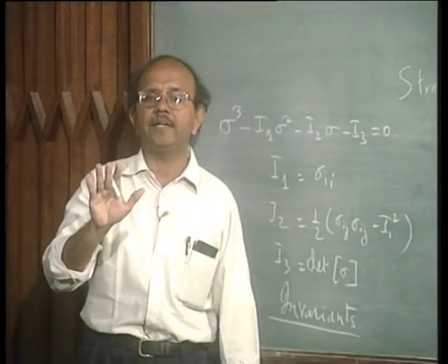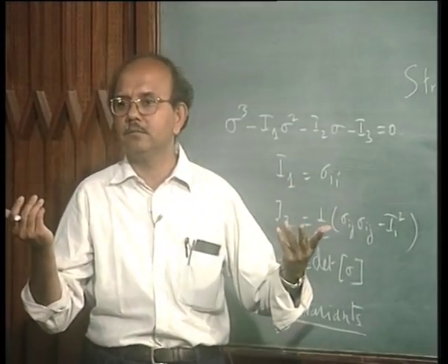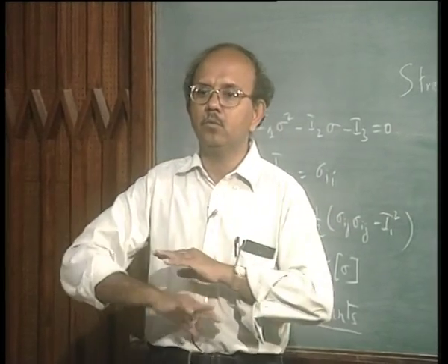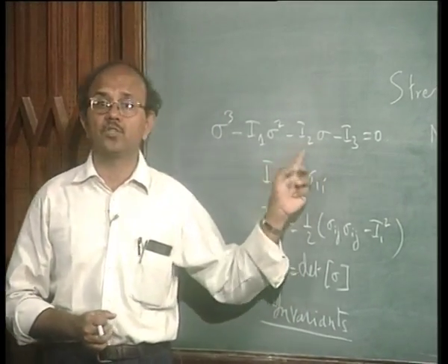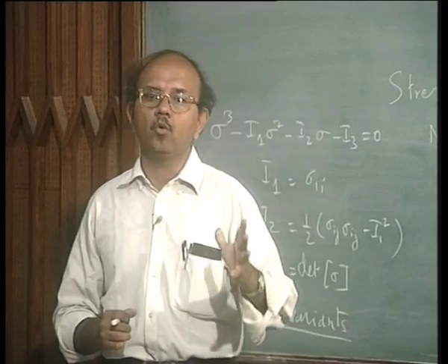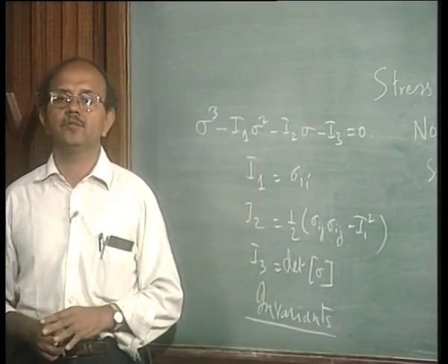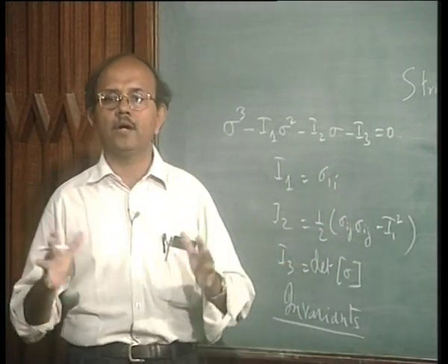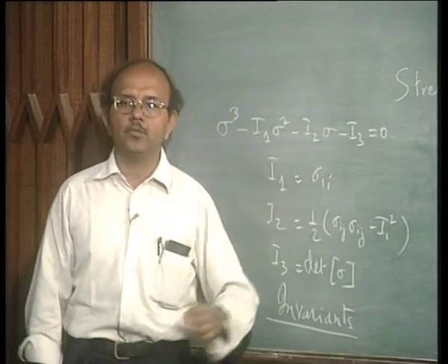It should be independent of the coordinates which I have selected, or else I can get whatever I want, because principal stresses have to be determined without the interference of these coordinates. So, what does it mean? It means that this equation which I am going to solve in order to get my sigmas should be invariant to the coordinate system. Hence, invariance signifies that they are independent of the coordinate system which you have used in order to get the cubic equation.